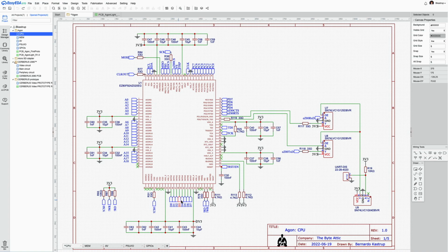They would also help on the data lines and address lines. But yeah, that goes too far. It would be too many resistors, and I didn't want to complicate my life that much. Moreover, in Agon, the data lines and the address lines are point-to-point lines. They have basically no fan-out, a fan-out of 1. They only go from the CPU to the memory, nowhere else. So you shouldn't have too much of an impedance mismatch or reflection problem there. So I didn't add those resistors in that case.